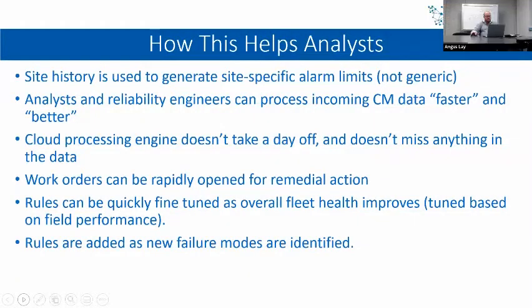Back to Angus. Okay, thanks, Matt. So yeah, how does this help the analysts or the reliability engineers or the supervisors on site that are having to review these large volumes of data? Well, one, in particular is, as Matt alluded to, our limits are set based off the historical data from your site, whereas the lab alerts are generally based on a large community. They are set at a higher limit, and this is mainly due to different operations having different operating conditions, maintenance strategies, even the lubricants and the skill sets as well, able to identify these issues.